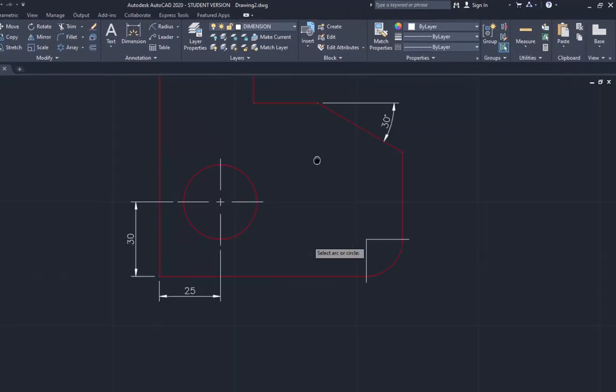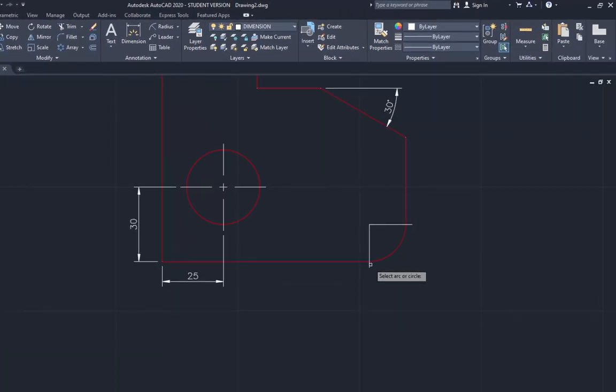So for example, this arc here is most likely to be made or marked out or machined, and the information that the operator would need in order to manufacture this part would be they'd need to know the radius of that curve. If they're marking it out on a piece of timber or a piece of steel or plastic, they would need to find this center point. They would then need to actually mark or scribe that radius. So it's the radius value that they need.